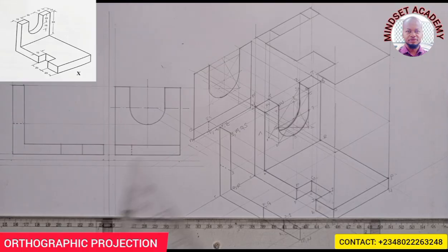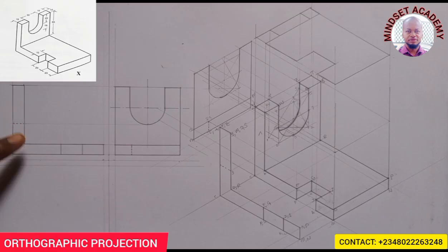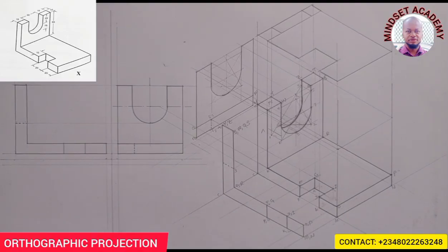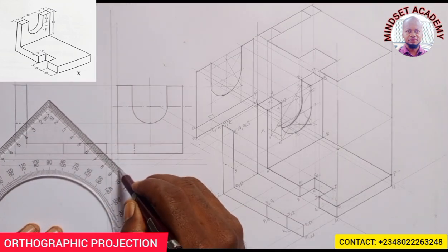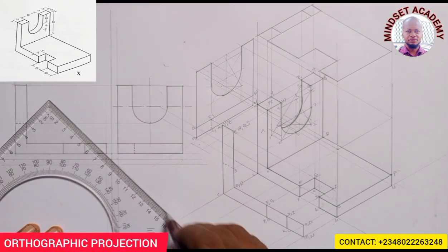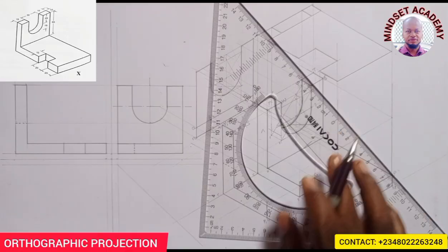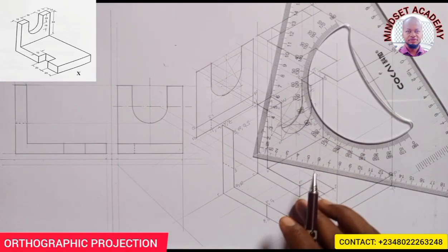Now the next thing is the plan. To get the plan, remember that the plan is always under the front elevation. So the plan will be here. So I will now use my instrument here, right? And I will draw an angle of what? 45 degrees from this point here, where I'm going to project this end point here. Then I'll take this in this way.